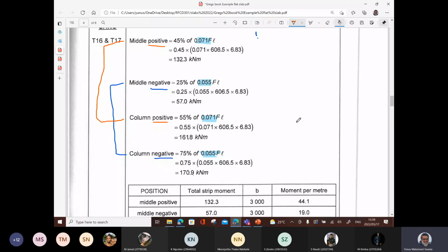The reason, if you remember that thing that I showed you, is that when you're on the column center line, your moment is peaking. Now this is from experiments. As you move away from the column center line, in a direction perpendicular to the length that you're considering, you'll find that the moment deviates and goes down a little bit. So just keep that in mind. I must get permission to share something with you from Marshall's book where he discusses those experiments.